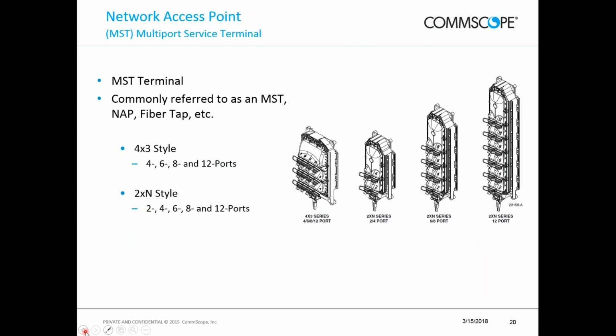Not to my knowledge. With every MST, and again, I'll point you to my laser pointer here, this area coming off of where I'm pointing to in the bottom of the MST, we refer to that as the tail. In this case, it would have 4 fibers in it. In the case of the 12 port, there's going to be 12 fibers in this. It looks like a flat drop cable design, but it would have 12 fibers in it.